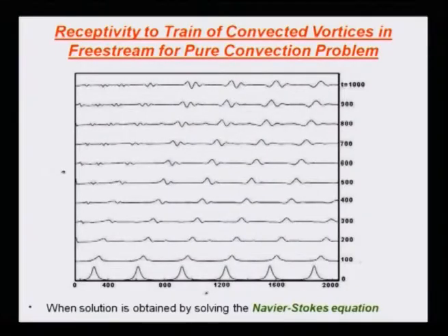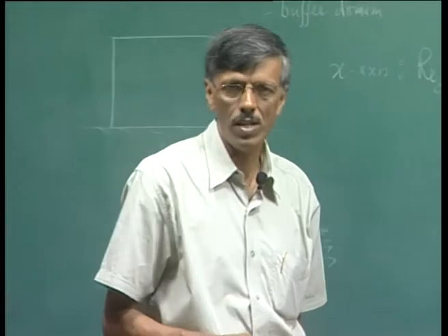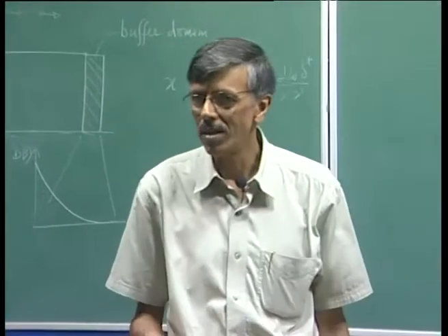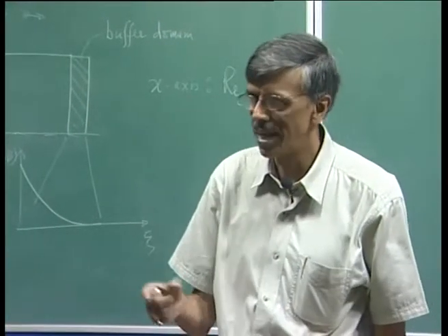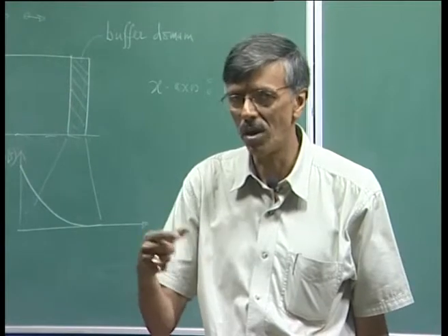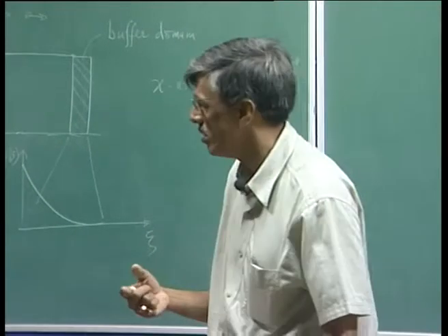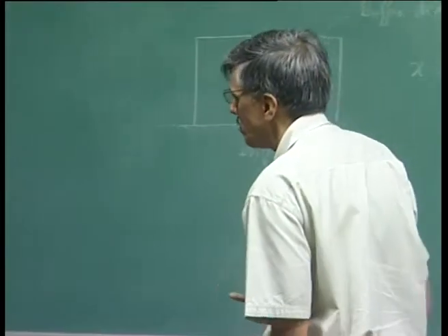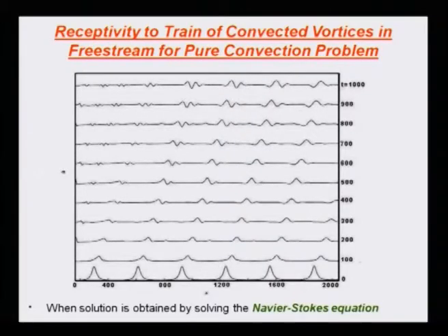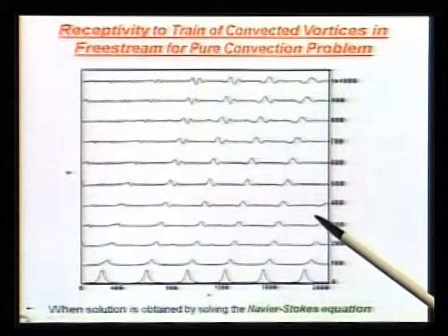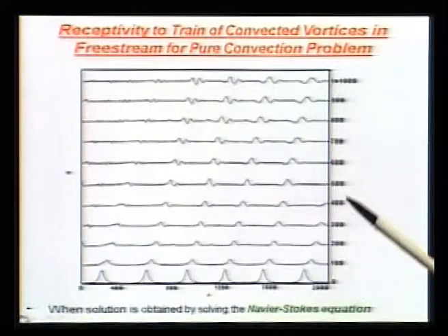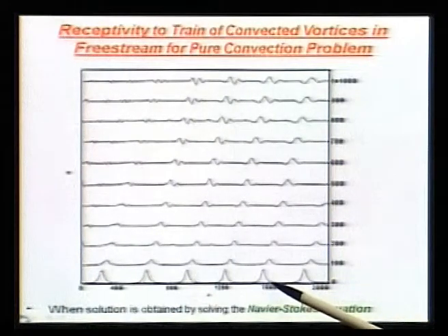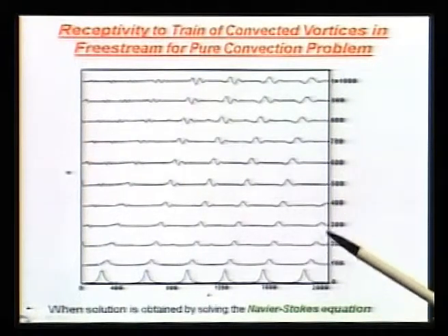We have also seen that it is a periodic excitation. If it is a periodic excitation, then I will have the excitation in terms of multiple frequencies. So, with time, I am going to see that if I have a peak corresponding to omega naught, I will also have a secondary peak corresponding to 2 omega naught and 3 omega naught.